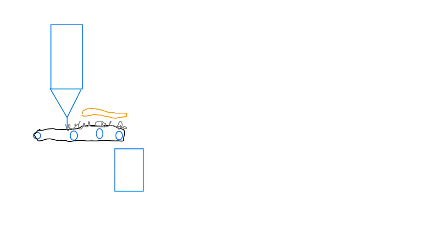Okay, so that is the first one. This is for 3 to 5 millimeter particles, and that's pretty easy and straightforward. So you'd probably put this in some sort of a cage so that you don't lose your radiative heat, so that the radiative heat is reflected back onto the belt. All right, so that's the first one.